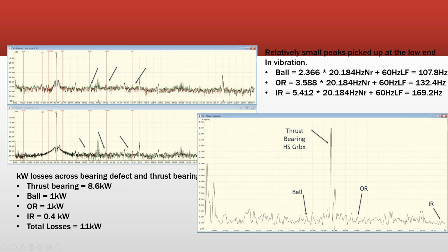So in a 60 Hertz environment, a 6-pole machine wants to operate at 1200. Now, if I go subsynchronous, so that my speed is less than 1200, then I won't generate power. So I have to go above 1200. So I'll do a pro-rotating field to whatever the set point is. And in the other case, I would do a counter-rotating field to slow down the magnetic field so that the fields cutting the stator and producing power are showing up as close to 60 Hertz as possible.